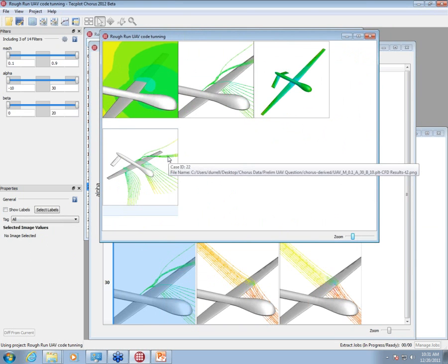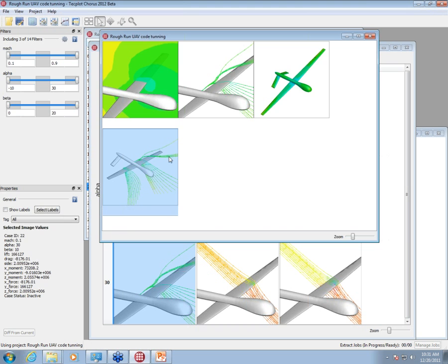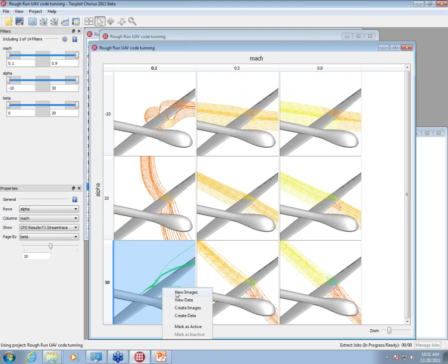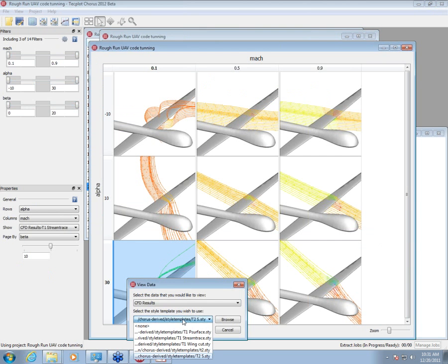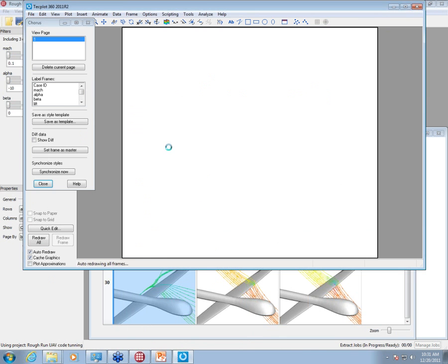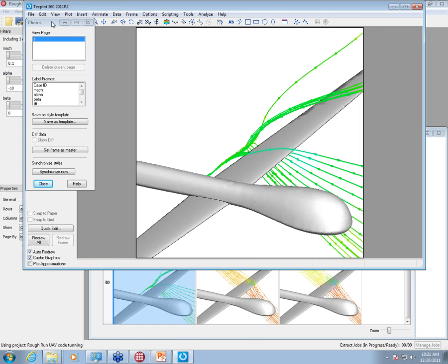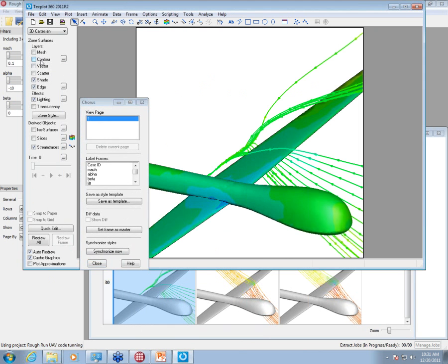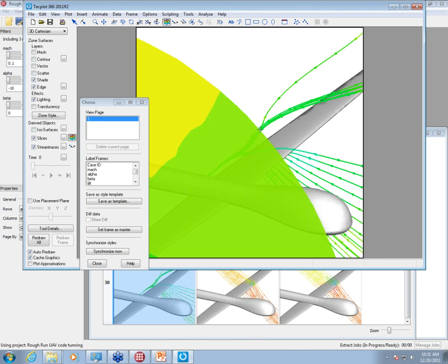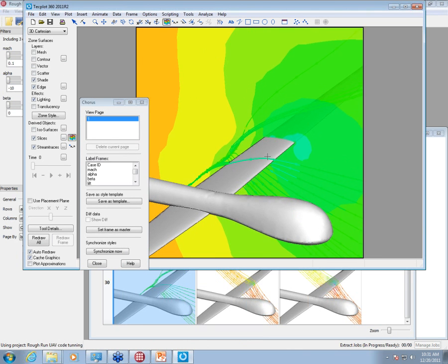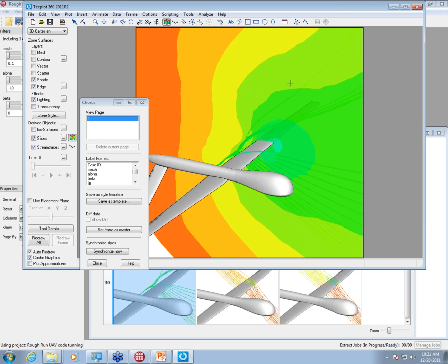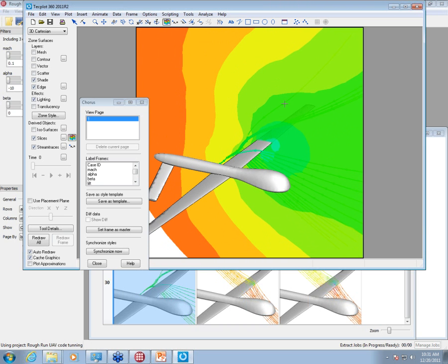And if you view the data on that, you'll see that in this case, there's clearly this pressure wave. You saw that a little bit in one of the images, but there's this pressure wave that is coming from the downstream boundary up. And so this is probably in the process of failing. It just hasn't failed yet. You can see that very high pressure downstream of the vehicle, and so this is a case you would want to remove from your analysis.